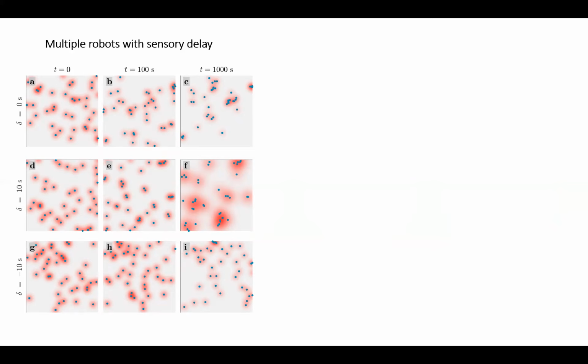This creates the sensor signal that is measured by each robot, and they are adjusting their velocity according to this measurement now. It's not an external signal or light field, but the cumulative signal that is coming from all the other robots surrounding them, okay? And then they follow the same idea. If they measure high signal, they move slower. If they measure low signal, exponentially, their velocity decays. And if they act with no delay, eventually they come close to each other. What happens is that if they act with positive delay, as a result, they come closer to each other. They accumulate or group together more. And if they apply negative delay in their velocity adjustment mechanism, they get further away from each other. So if you think about it, this is very useful. Why?